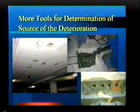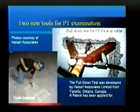Post-tension. If you get into post-tension, we have to do some excavations just to find the cables. And now how much stress is actually on the cable? What we used to have to do is we'd have to cut the bar, cut the PT, put a locking device on it, and pull it. I can tell you how much is there. Okay. A couple new devices.